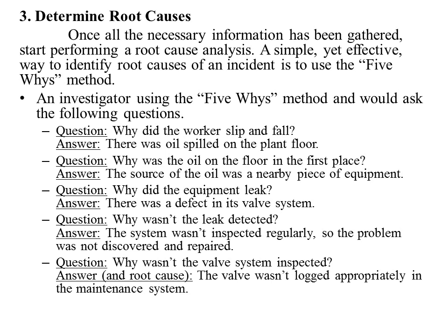The reason here is that the inspection was not done properly, and whatever defect was there was not written down properly in the maintenance system, in the logbook. So this is just an example of how an investigator would arrive at the root cause of an accident. Of course, he need not be restricted to just 5 questions. It may go beyond 5 questions or even fewer, depending on the type of accident.